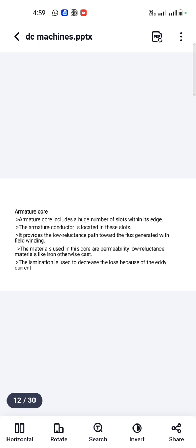So we have one doubt, right? What is eddy current loss? Actually, it's a current only. It is a circulating current, because in a coil the current flows in a circulating path, right? In that circulating current, some unwanted currents flow in the core. It produces heat that causes energy loss. That we call eddy current loss. This armature core provides a magnetic path, right?